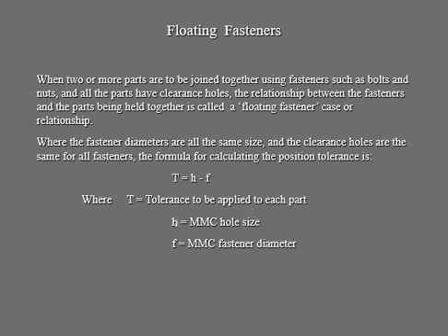We get the maximum material condition hole size, and then minus the maximum material condition fastener diameter. Then you get the tolerance to be applied to each part.